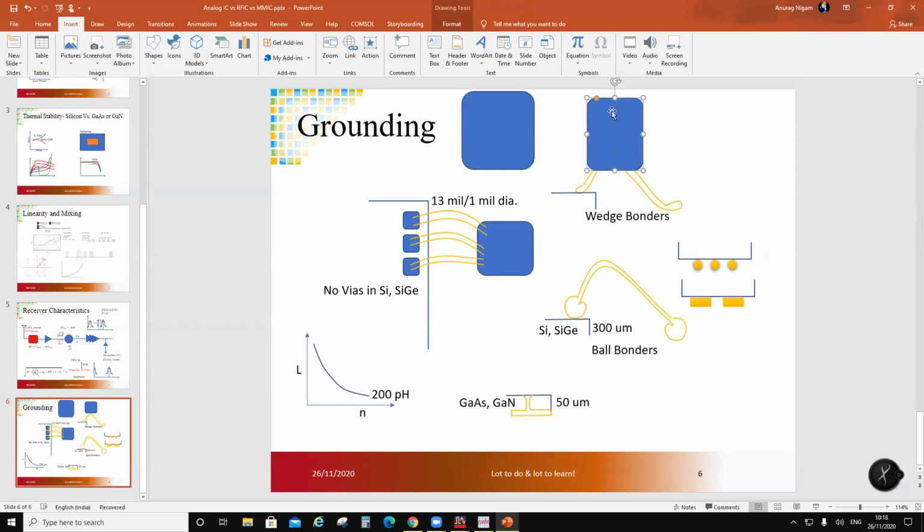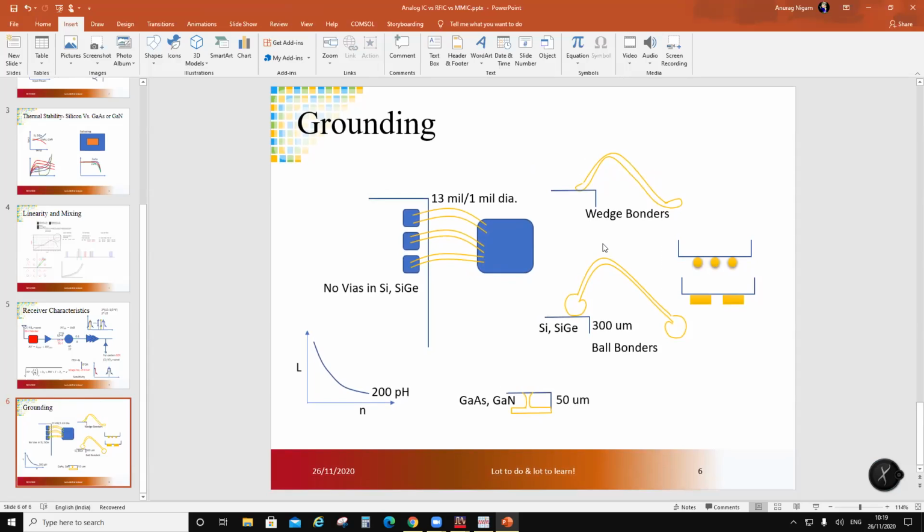These pads have to be bigger because you are doing Z current modeling. If you have a discontinuity here and your SMD sits right at the edge, how does the simulator model the Z current? So you have to make these pads bigger, and the component should fit on them. Then you can model the Z currents in your EM simulation. If it is there in reality, it has to be there in your simulation. You cannot be an ignorant guy and then say, let's blame it on the model. That's wrong. That's what I have observed in 15 years in India.